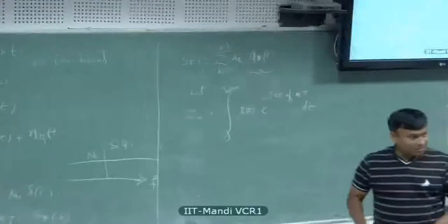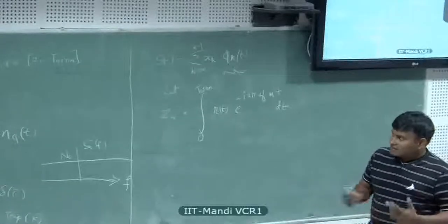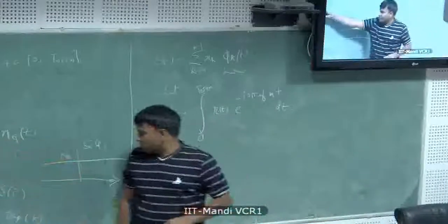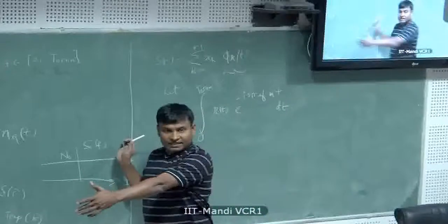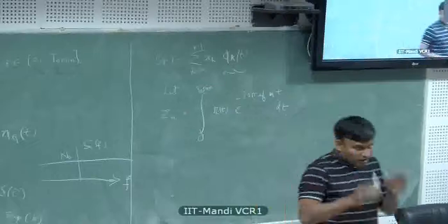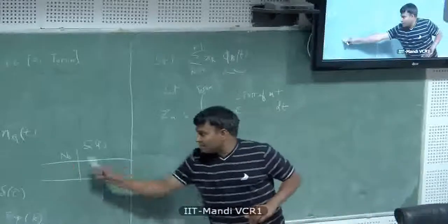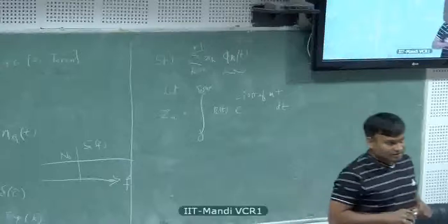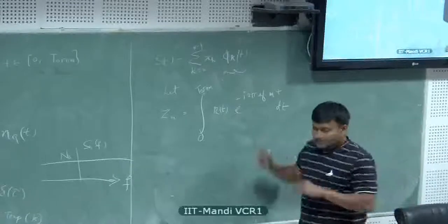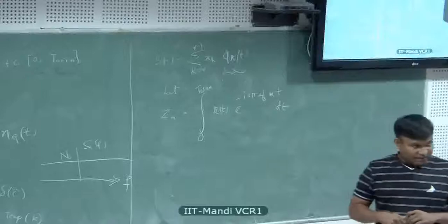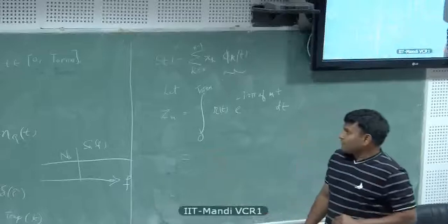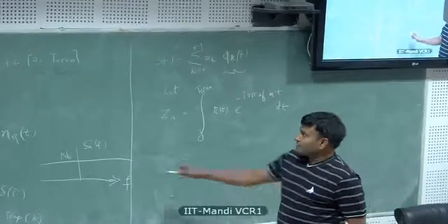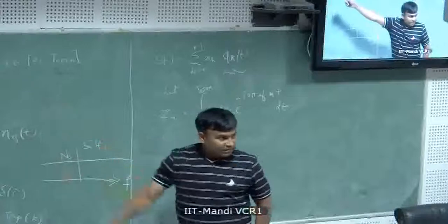Of course, this whole thing is again low pass baseband. Carrier up conversion and down conversion have been carried out. And sometimes this N of t need not be totally flat. You could have a front end band pass filter with a very wide bandwidth, but that's okay. That doesn't change anything as long as you have a spectrum that is flat. Okay, that's good enough. We'll come to those things later, but we'll keep the system very highly idealized for the time being. So R of t is S of t plus N of t, and S of t is whatever the transmitted signal. We'll write it.